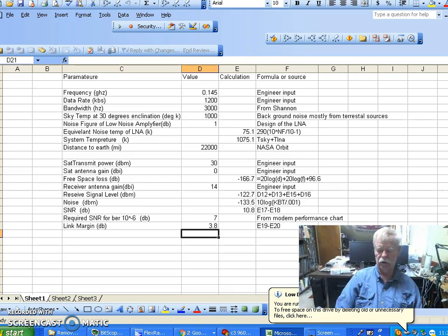The next thing you have to design is the antenna on the satellite. It turns out, and I'll try to highlight this as we go, that if we can produce an antenna on the satellite that essentially puts out radiation in all directions, you describe that antenna as having a gain of 0 dB. Tough to do on our satellite, but we've got to plug a number in here, and we choose to plug the gain of the transmit antenna at 0.